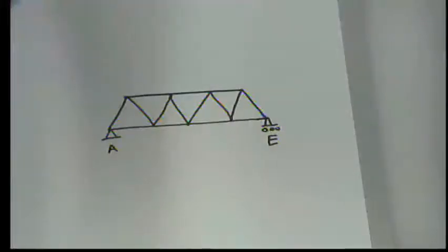We already know stuff. We know that each one of those structural members is in tension or compression or in zero stress. And we know that we can do the analysis of the tension or compression in each of these structural members based on, first of all, doing a good free body diagram of the entire structure, and then second of all, looking at each joint or each connection where the structural members go into each other in order to figure out whether the structural member in question is in tension or compression.